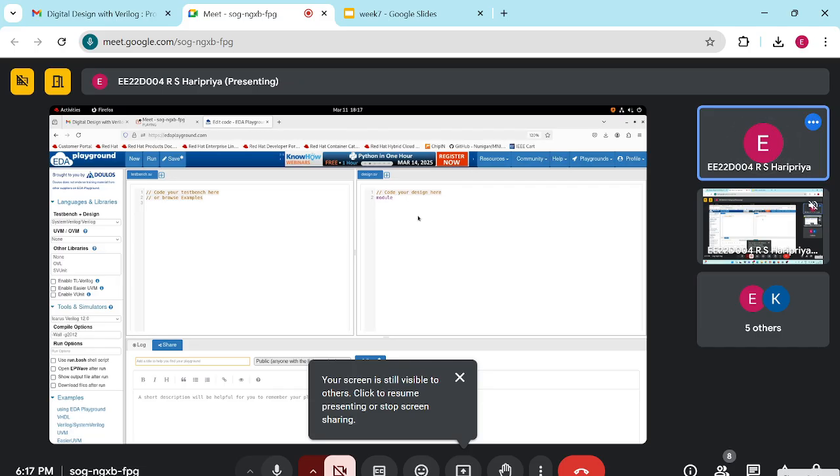Module half adder, and the port list S, C, X, and Y. In this, inputs are X and Y, and outputs are S, comma C. If we write the gate-level implementation, for the sum it is X XOR Y, so output followed by input, and the carry C is AND of X and Y. So fine, this is the module for the half adder.